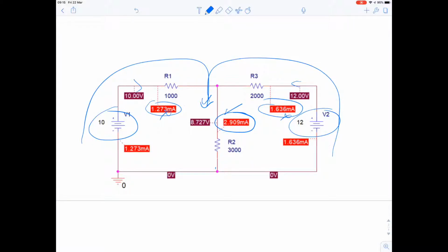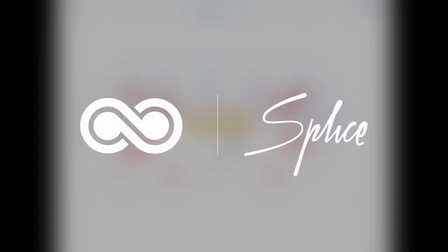But what I have managed to find, and quite clearly I found this value, and I found the voltage across that resistor. So superposition, an awful lot simpler than, say, doing a Kirchhoff's voltage law and lots of equations. Nice and simple, and a quick calculation. All we needed to know here was how to rearrange the circuit, parallel resistance, series resistance, and of course current divider rule.